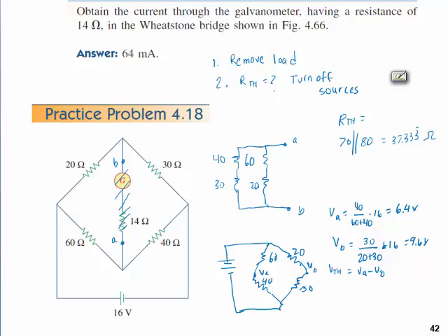In the way I've drawn it, that actually gives me a negative voltage, but that's okay. That doesn't affect us. It's 6.4 minus 9.6, which is negative 3.2 volts. So really we know that voltage B is higher than voltage A because I got a negative value, and my assumption is that A is positive and B is the lower potential.